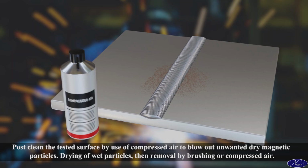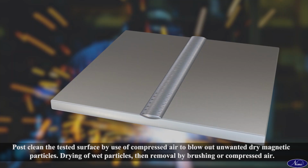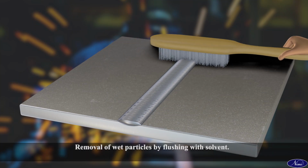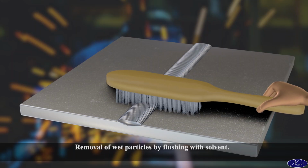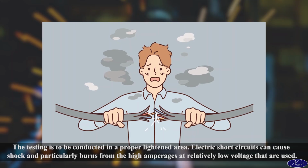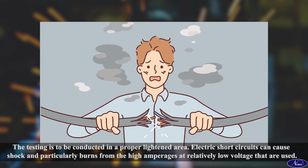Post-clean the tested surface by use of compressed air to blow out unwanted dry magnetic particles. Drying of wet particles, then removal by brushing or compressed air. Removal of wet particles by flushing with solvent. The testing is to be conducted in a properly lighted area. Electrical short circuits can cause shock and particularly burns from the high amperage at the relatively low voltage that is used.